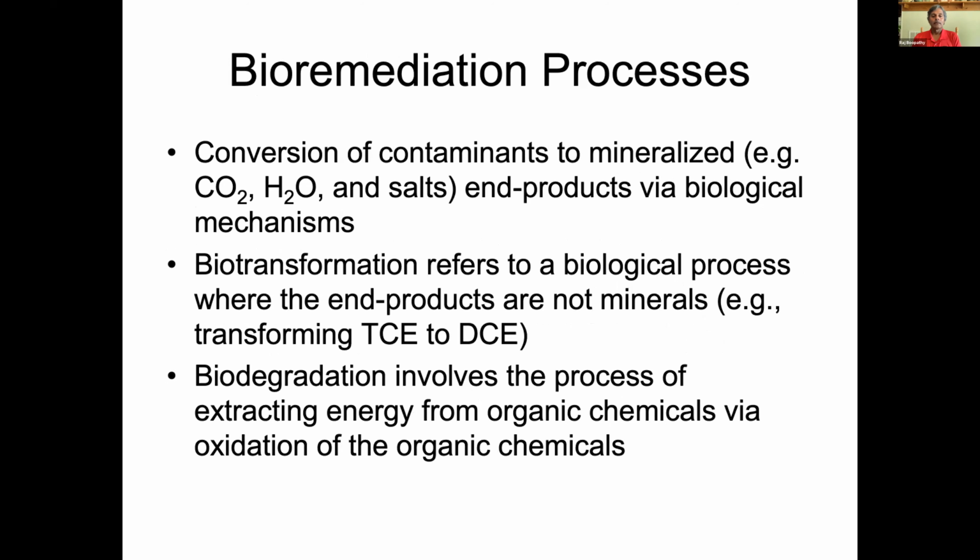So as I said, there are a lot of chemicals we throw out, like halogenated compounds such as TCE and PCE. The bacteria have an option of completely mineralizing them, which is obviously the good thing that we want. Sometimes they just modify and biotransform them, reducing their toxicity. For example, TCE can be dehalogenated to dichloroethylene instead of trichloroethylene. So you slightly change the structure of the compound, which is biotransformation.